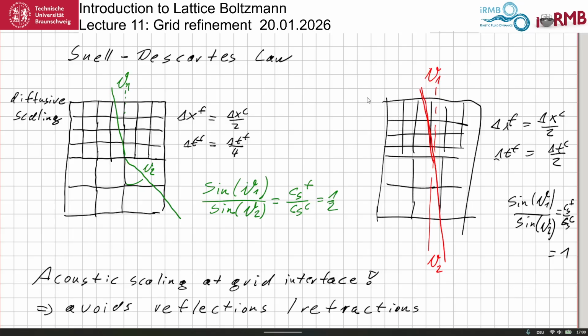And now if you go over the interface, the only thing you reconstruct is from the Navier-Stokes equation. So you're reconstructing the gradient from the velocity. So you have this offset on one side, in the actual simulation domain, and your reconstruction does not have this offset. This generates a discrepancy, and this can generate spurious oscillations. This is what you observe there.